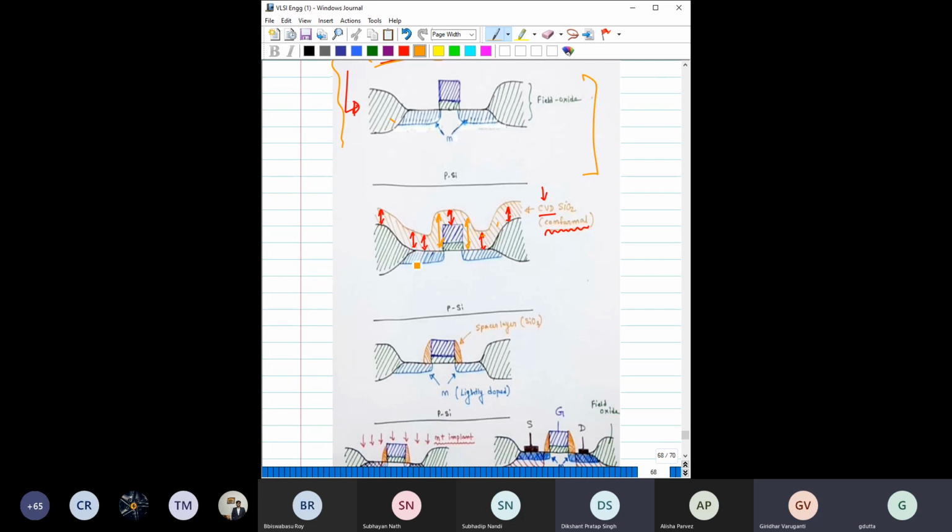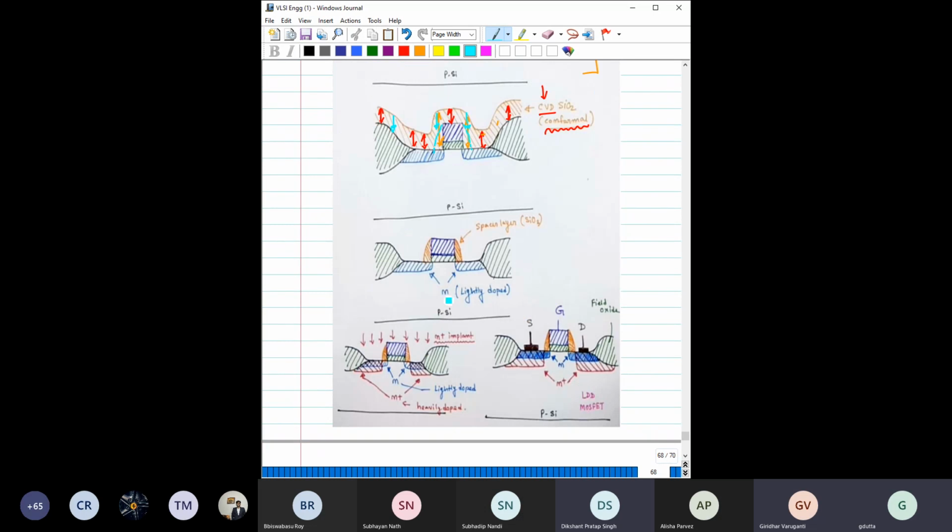Then you etch the silicon dioxide exactly by this amount. You have different dry etching techniques, so use those to etch this oxide layer by this amount. You etch this amount here, and this amount here. But at the gate edge, the same thickness is etched, so after this etching you will be left with this much oxide.